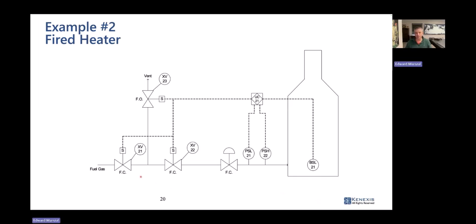So in a 1 out of 2 system, there are 2 valves: valve number 1, valve number 2. The M is how many devices need to take an action to get to a safe state. So how many are required to vote to trip in order for the trip to happen? And in this case, we said it was 1 out of 2.